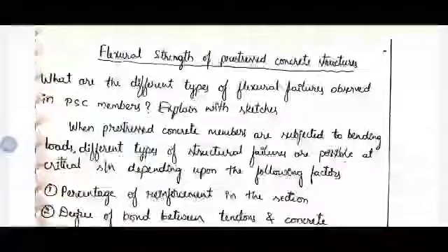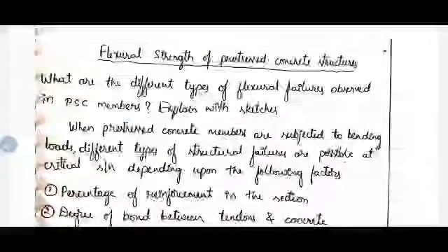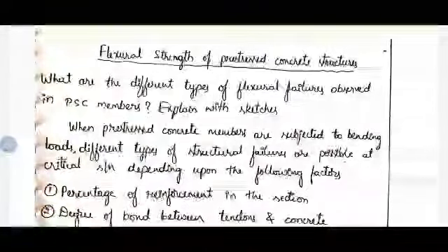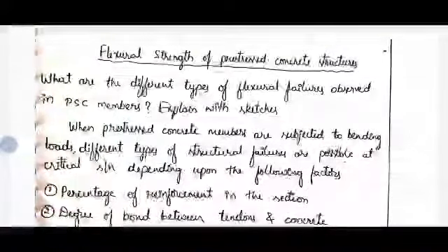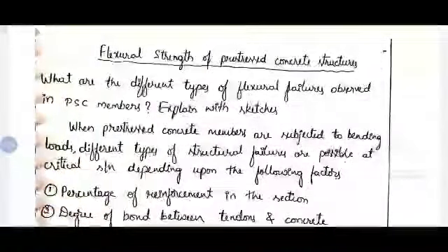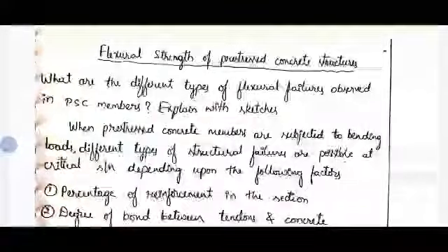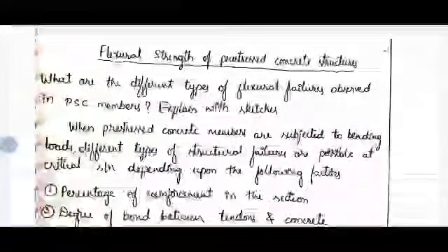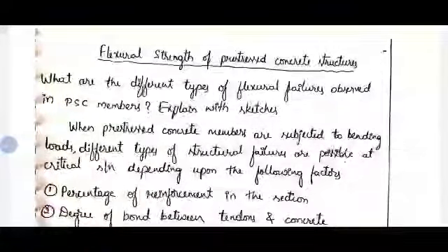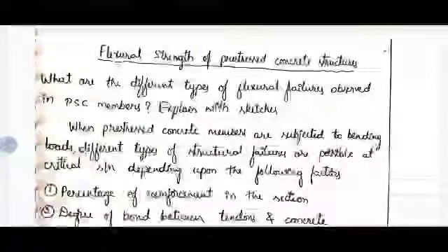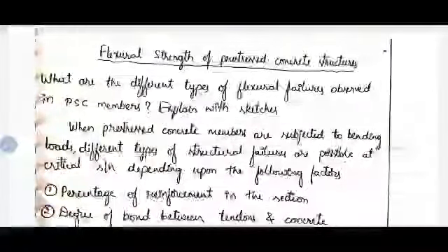In PSC we have 3 types of flexural members, so among the 3 types we have only type 1 design. In PSC we carry out the design in 2 different steps. One is preliminary design, then pre-stressing design. In preliminary design we are going to find out the cross section of the member required, the length, the span, the width of the beam, the depth of the beam. Then in the second part we are going to analyze the section, and by the analysis result we are going to design the pre-stressing force we need to induce and the cable profile, all those things.